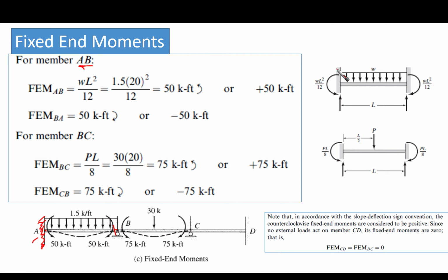So it is considered as if it is fixed. We are going to put the analogy as this is point A, this is point B. You can find this in the references in the back cover of the textbook. You will find the distributed load with fixed end moments for this case, which is spanning L with W distributed load, which is the first case as I mentioned before.